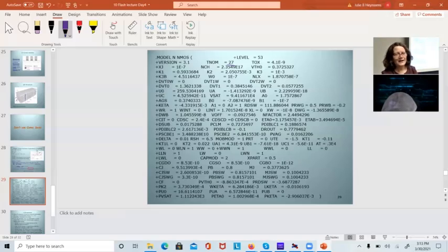Really low. Yeah, and that's where SPICE's model just completely falls apart. So I had to do this because we were actually spending $1 million to build a new chip, and we had to know what it was going to be, and we were changing the unit cell. It was an imager, and imagers act like DRAM memories. Instead of using the 1T 1C, they use an old school 3T 1 photodiode cell, and we changed it